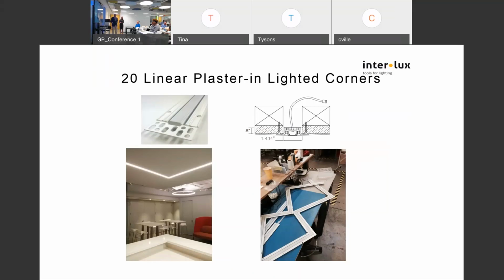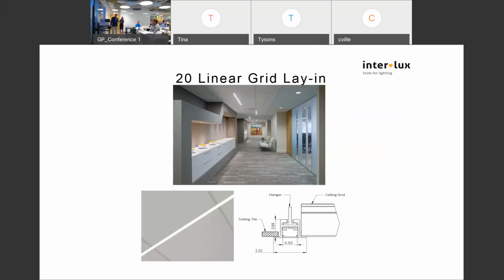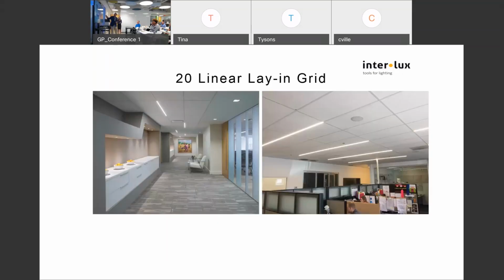It's brilliant, just the way you're thinking about the space coming together like that. And I just passed around the surface mount. So when the surface mount is too big, 20 millimeters below the sealant plane, you ask your designer, can you recess it? So now we recess it into the T-bar grid as well. So again, any length, any shape.